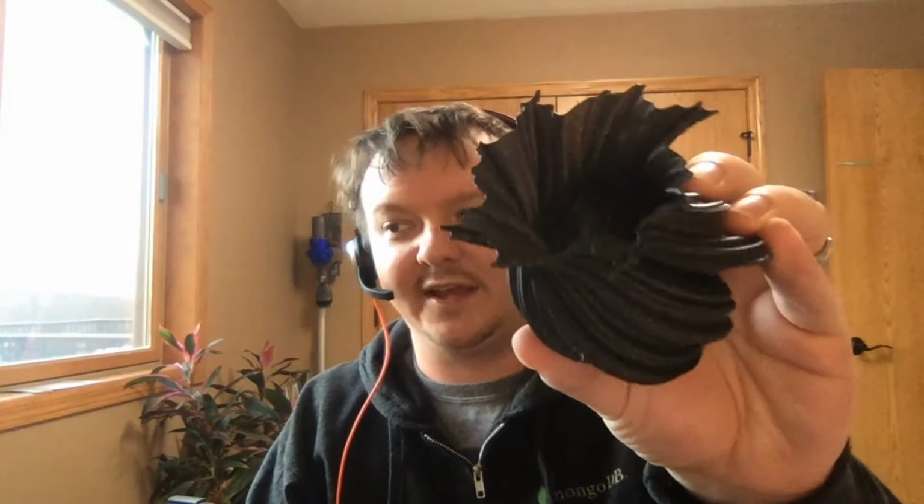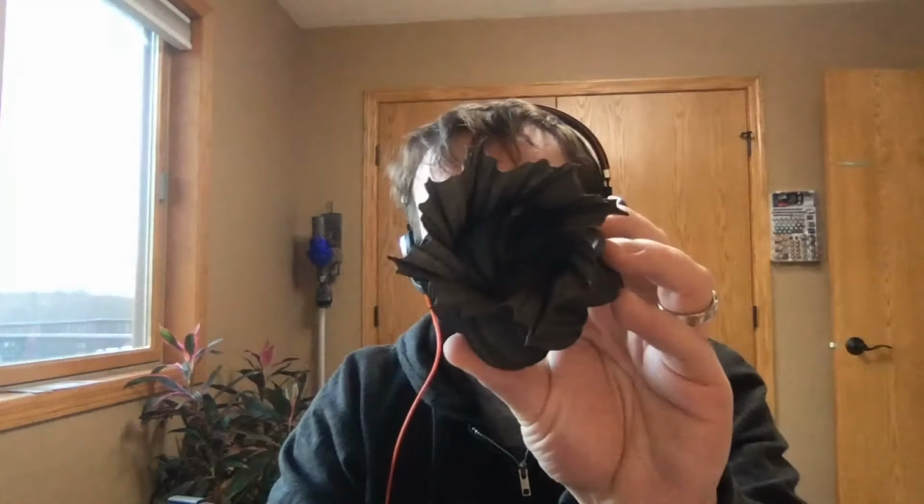I'll show you a version of this printing. This prints in what you call vase mode. So this is only a single line wide, and this makes it really fast to print because the nozzle never has to stop. It just does one continuous fractal pattern, basically, in this case. But it just slowly increases in size as it goes up.